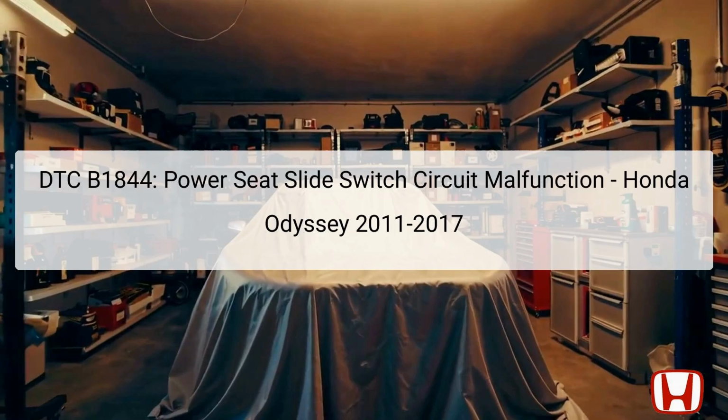The power seat control unit connected to this switch plays a crucial role in translating the input from the switch into action, activating the motor to adjust the seat position. When B1844 is recorded, it's necessary to follow a structured troubleshooting process to diagnose the specific malfunction. The error may stem from several areas, including the switch itself, the control unit, wiring issues, or even related components, necessitating a systematic approach to identify and rectify the underlying problem.